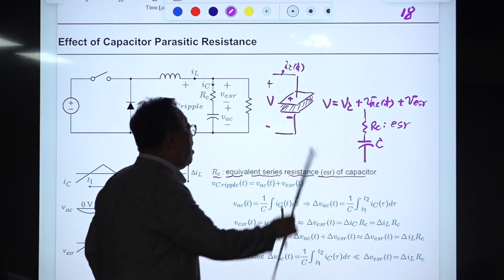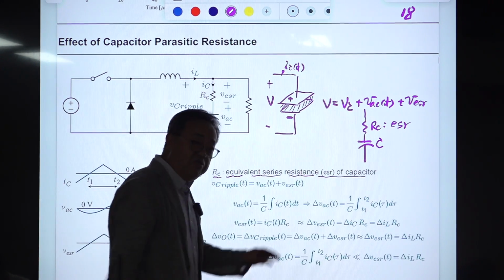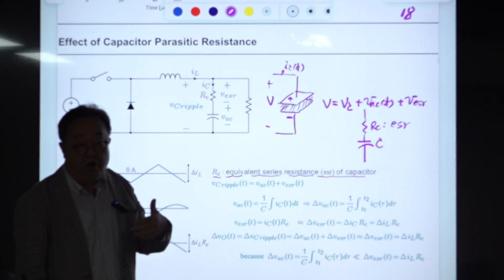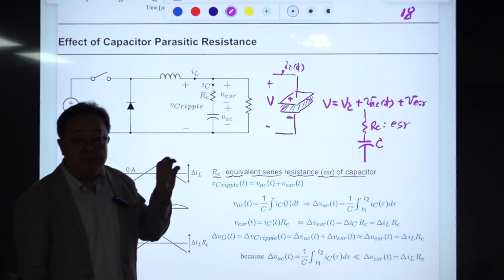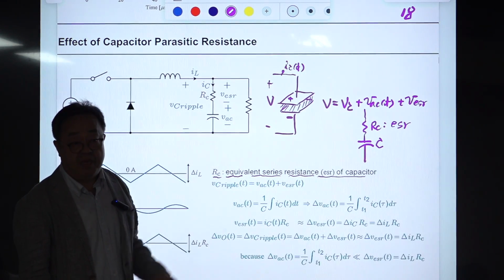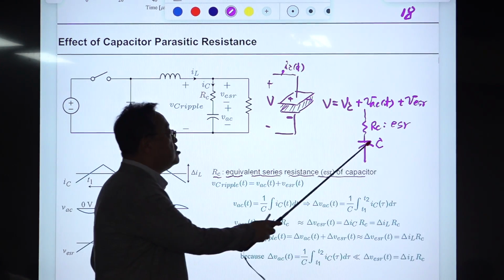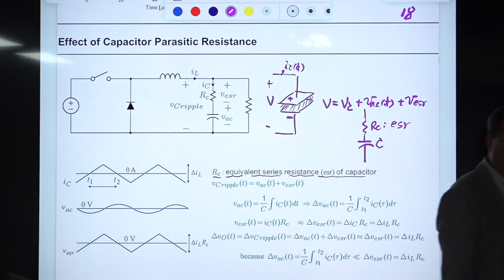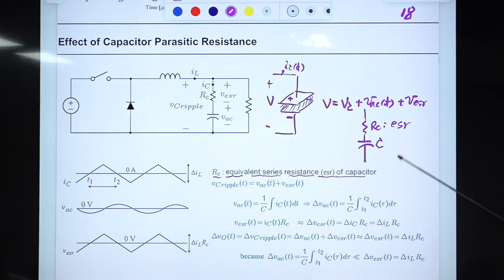Then it has large RC, then you have ESR, which boosts the phase characteristic of everything. The converter predicts stability, okay? Now you change this capacitor for an expensive one, like MLCC or some fancy one, with very small ESR, negligible ESR, then the converter immediately becomes unstable, right? Then you will be puzzled, right?